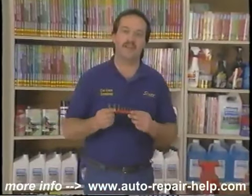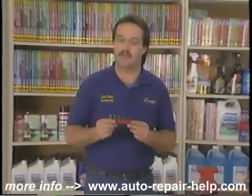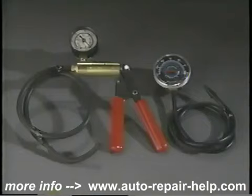So you'll most likely need a set of Torx bits that I suggest you get from size 10 through size 50. For General Motors carbureted vehicles newer than 1980, you'll need some of these special tools for making fine-tuning adjustments either during a carburetor overhaul or even during an engine tune-up. Now, another couple of common troubleshooting tools are a hand vacuum pump and a handheld vacuum pressure tester.